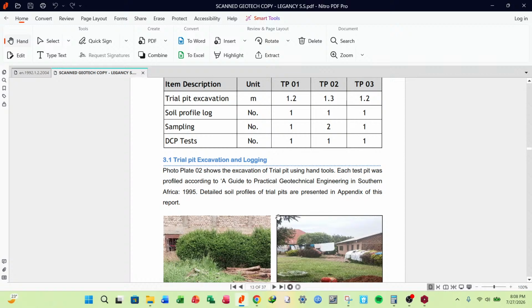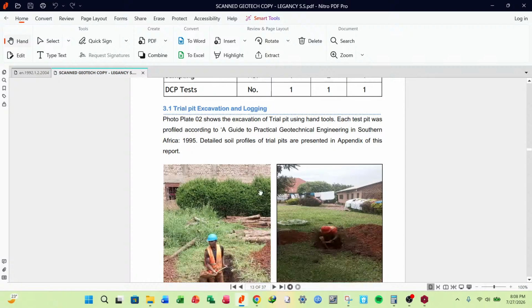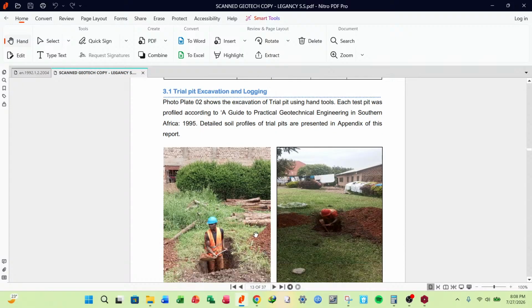It can also affect the assumptions you make when designing your ground beams. When the soils are too weak, you may be forced to design your ground beams as tie beams, as suspended beams actually, suspended at the ground floor level, because you cannot rely on the topsoil onto which the strip footing rests.